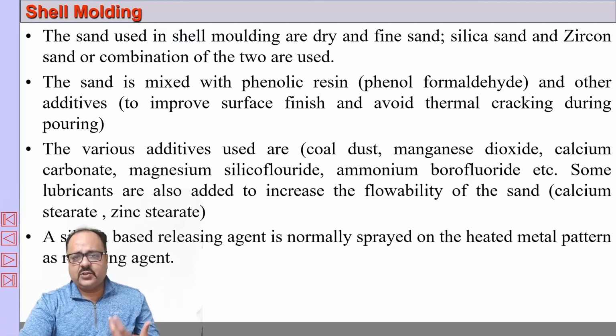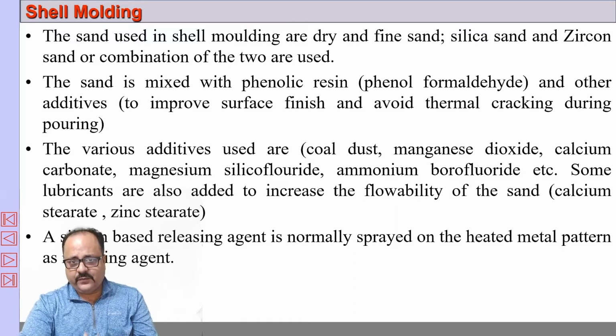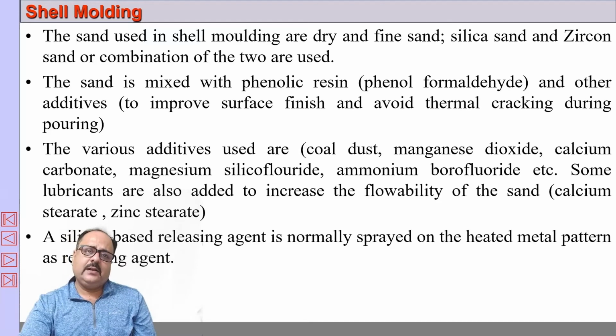And the sand is also mixed with a phenolic resin, which is basically phenol formaldehyde, and this phenol formaldehyde is used to improve the surface finish and avoid thermal cracking. And this phenolic resin, this phenol formaldehyde, undergoes thermosetting and becomes stiff and helps in the formation of the shell.